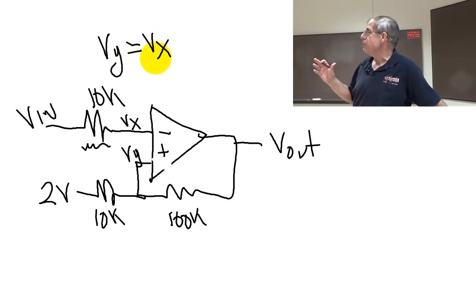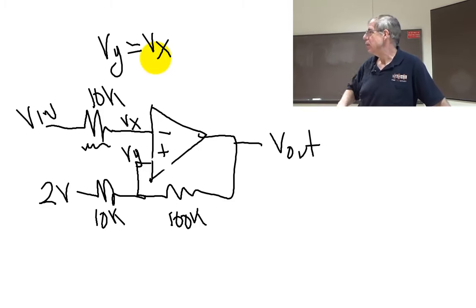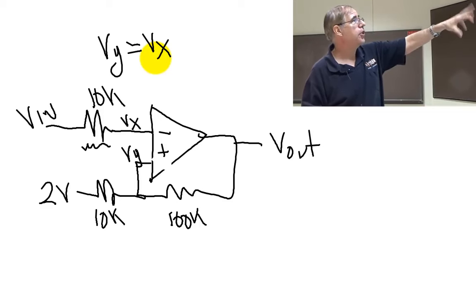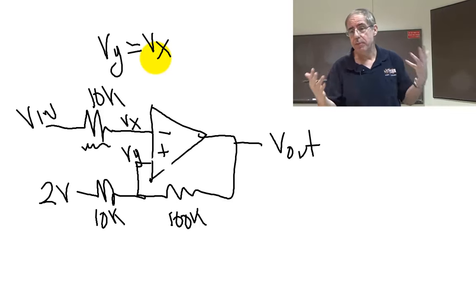You remember negative feedback caused them to be equal. Okay? But here in positive feedback, they're not going to be equal. But something interesting happens when they are. Okay? When they are equal, that's when it switches. That's when it flips. That's the time in which it will flip the mode and cause the output to go from 0 to 3.3 or 3.3 to 0.